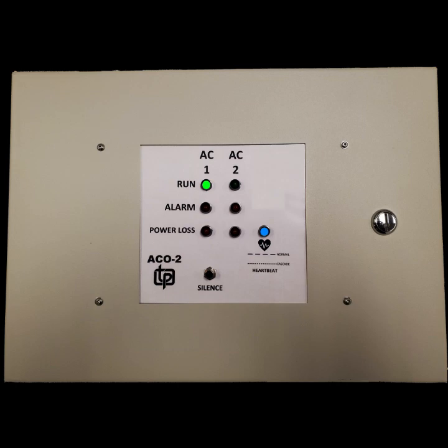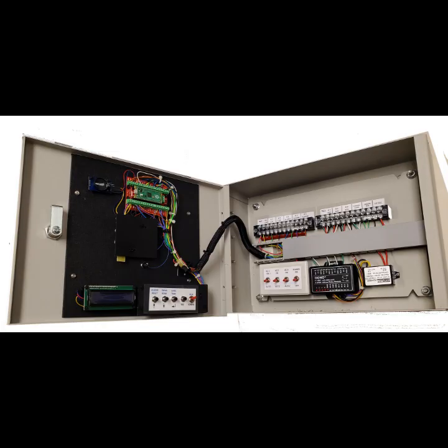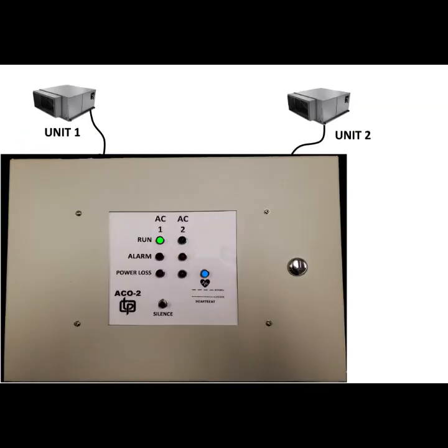The Tech Plan ACO is ideal for coordinated control of Liebert AC systems to provide redundancy. It was designed with the Liebert units in mind, but it could also work for pumps or other systems that use a dry contact for control. When the ACO controller detects an alarm on an operating unit, the ACO enables a standby unit and, depending on the configuration, either leaves the unit in alarm operating or shuts it down.